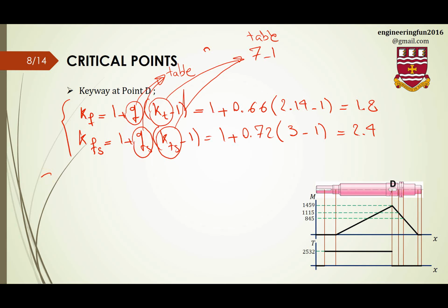Now, if we come back to chapter 6, here we face a dynamic load, so we need to analyze a dynamic question. We need to find endurance strength, and we said that in order to find endurance strength, first we need to find SUT, then we need to find Se prime, then we need to find Se.